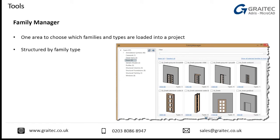So I'll go through the tools in the PowerPoint and then I'll show you how they work. The first tool that I'll be showing you is the Family Manager, and the Family Manager is a really useful tool. If you've got your own internal libraries for Revit, this will give you the ability to not only put that into a central library where we can access it, but we can load multiple objects from the libraries at the same time. It will then also ask me, out of the libraries that I'm loading, which sizes I want.